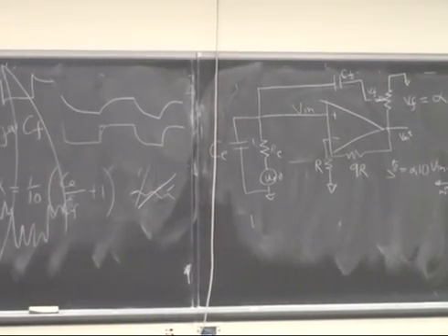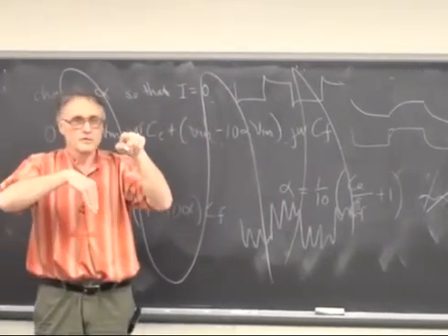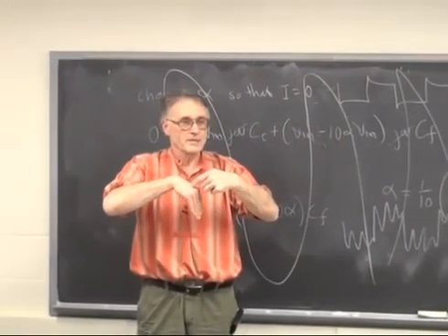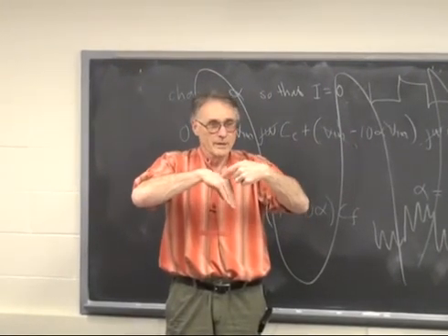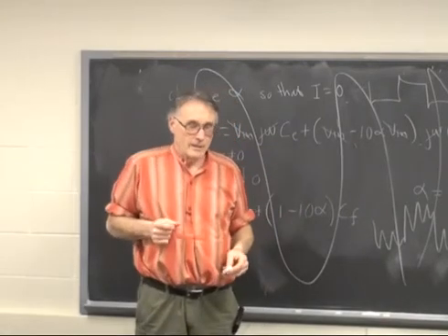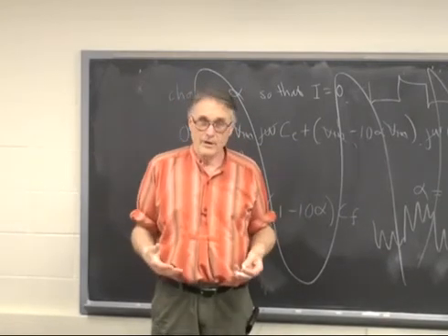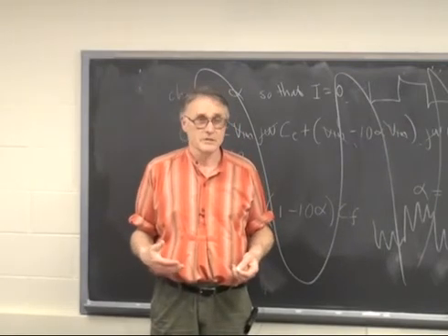You put the electrode against the cell but not in the cell, push the button, and it jacks the negative capacitance feedback to full, blows a hole in the membrane, and the electrode slides in. But that suggests that if you accidentally turn up the gain too far while you're inside of a cell, it just demolishes the cell, and it does.